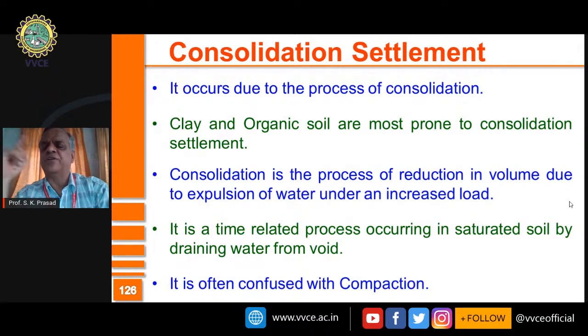Consolidation is the process of reduction in volume of the soil mass. Why will it reduce? Because of the expulsion of water under increased load. It's the reduction in volume because of the removal of water from it. It's a time consuming process. It takes a long time for water to go out, and the time required will be equal to how much distance the water has to move to release the pressure.